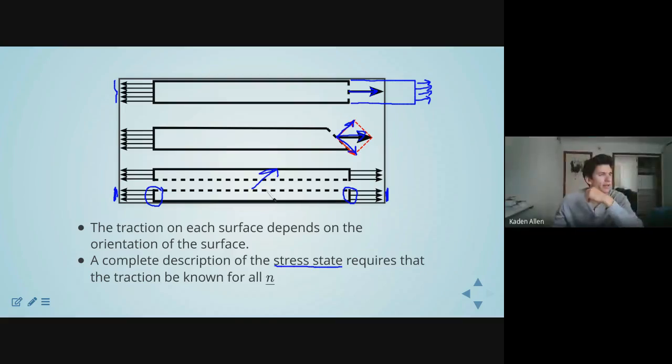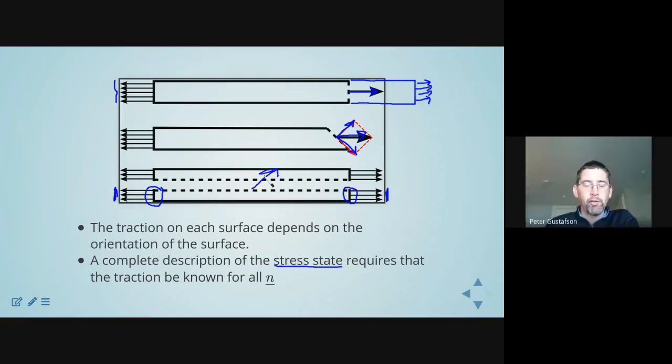So it's more about whether you interrupt the flow of the stress. Well, it's more applying equilibrium, and you can think about it as interrupting the flow of the stress. We will talk about flow as load is flowing through the structure. The reality is that you can actually think of it as a flow if you so choose to, but really this is just application of equilibrium.